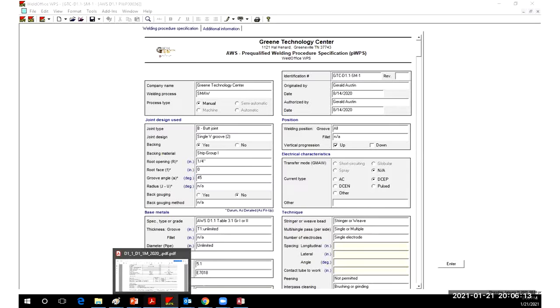Correct. There's no linking between the performance qualification WPS and the WPS that's going to be used in production. So the welder is qualified regardless of what WPS he uses in the future, and even who issues it. There's nothing that prohibits that in D1.1 and in any other codes other than ASME Section 9, which is specific because the manufacturer, the contractor, has to do the testing. So that one's kind of different.